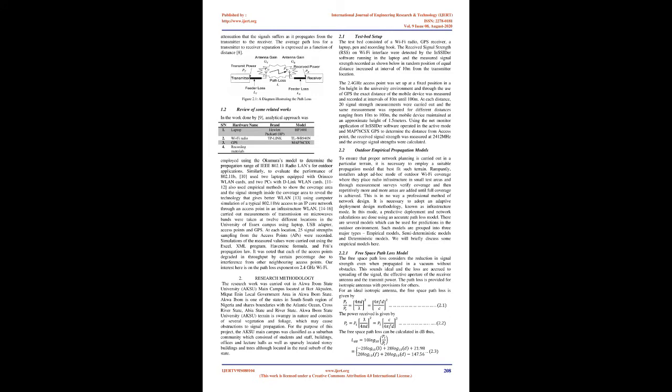1.1 Review of outdoor signal propagation. In reality, the amount of power transmitted from the transmitter usually reduces as it passes through a medium, hence, the signal strength is said to be degrading with distance. Path loss is the difference in dB between the transmitted power and the received power, and represents signal level attenuation caused by free space propagation, reflection, diffraction, and scattering as a result of obstacles on the path of the signal.